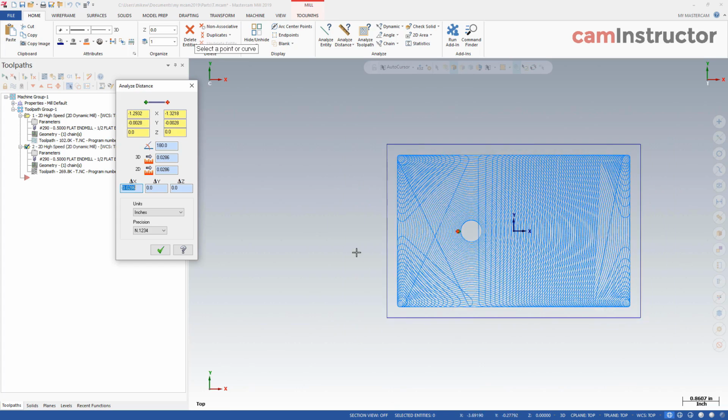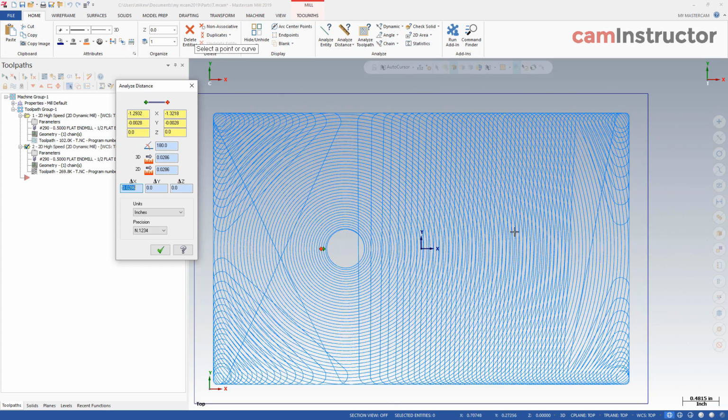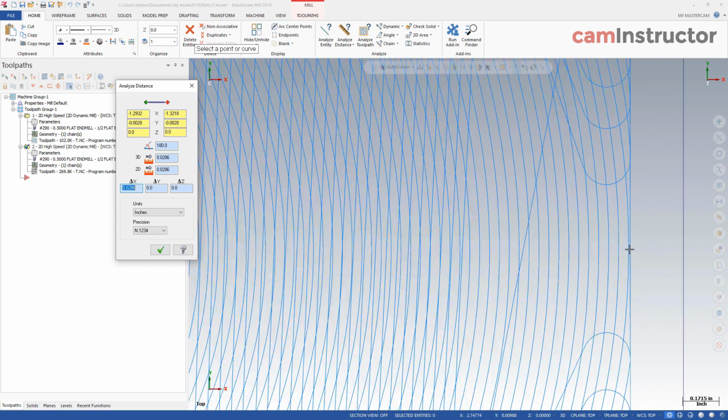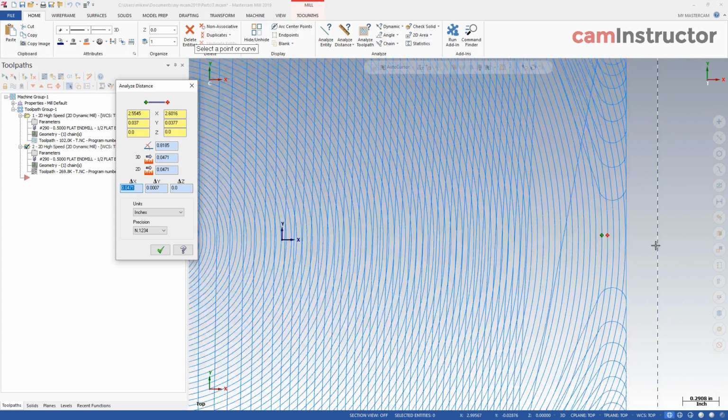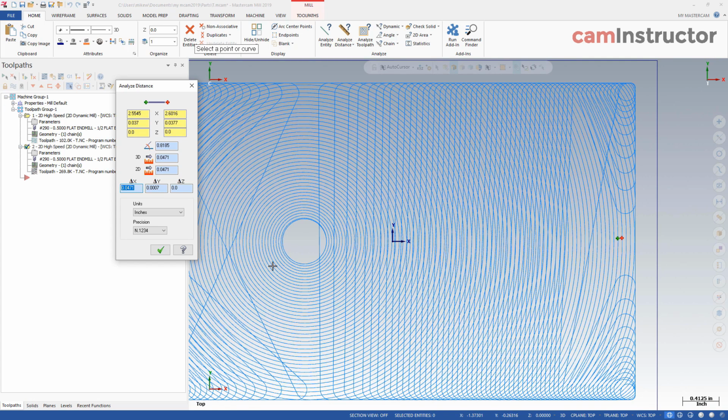You know, we'll kind of look past some of the feeding motions for repositions, but over in this area, let's say about from there to about there. Again, it might be a little bit off, but now we're seeing something closer to 50 thou. So why, again, back to the same question, back in this smaller arcing area, it's way less than our specified 50 thou step over, and as we get into these larger curves, it's getting much closer.